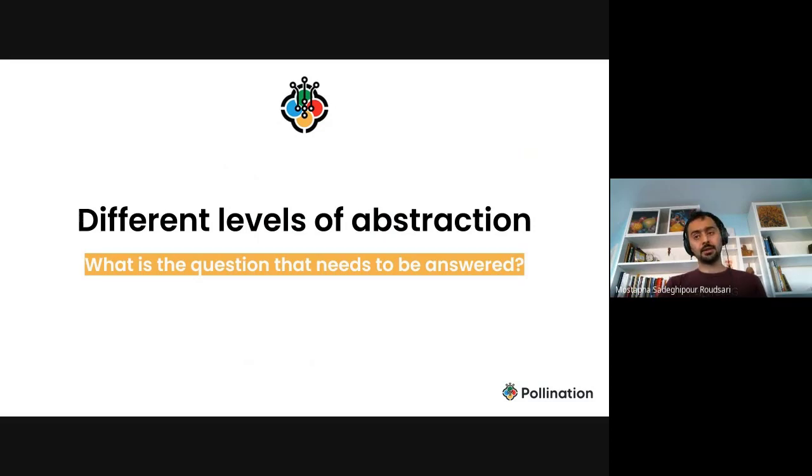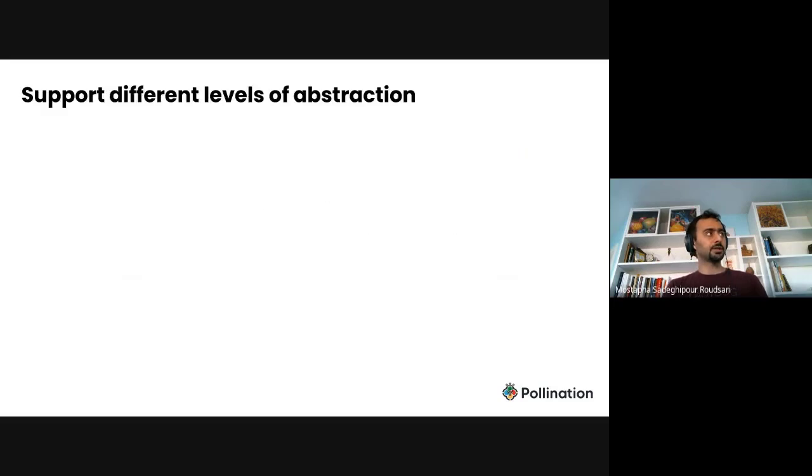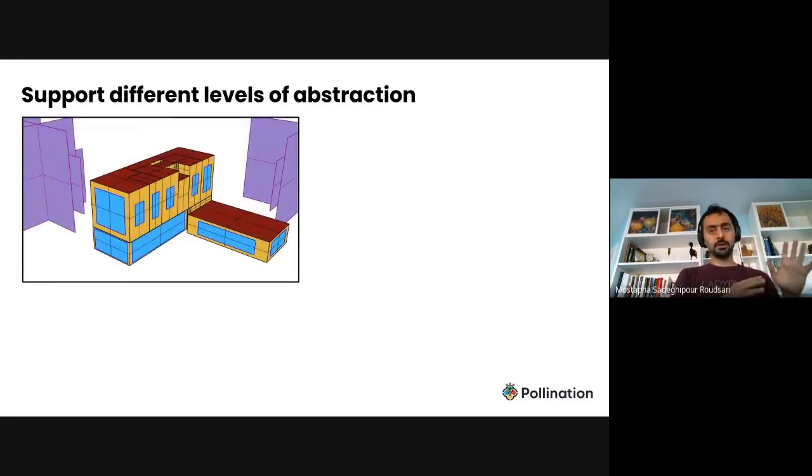This goes back to the thing that I said, there is no single analytical model. So we support different levels of abstraction. The first one is what we call the Dragonfly model, which we initially designed for urban studies, but now we found it very useful for load calculation, basically simulations where you don't need detailed geometry. Mostly you want to get the area, base and volume of the model. When the model is not clean, this usually works the greatest because you have the lines, right? And it extrudes up. It adds all the apertures, calculates the area, puts it on the window.